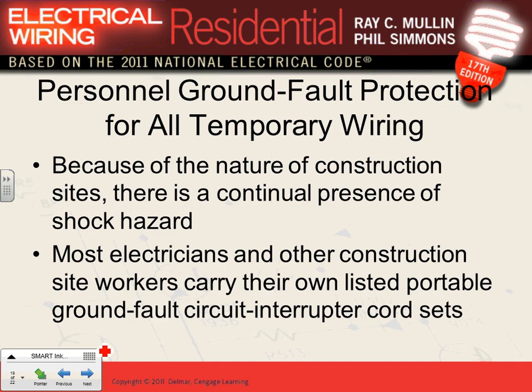Temporary wiring. So everybody knows where arc fault circuit interrupters, GFCI, tamper resistance, weatherproof, weather resistance are required, right? Can I have thumbs up one more time before I move into a different topic? Temporary wiring. Temporary wiring could be for decoration, or it could be for the construction site. If you're doing temporary wiring for construction decoration, typically 90 days, construction until the duration of the project.